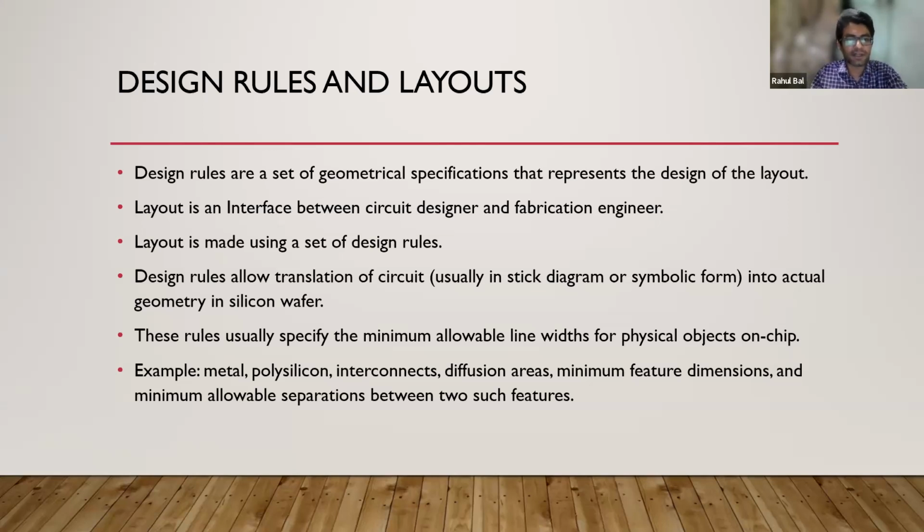That's why it is the interface between circuit designer and fabrication engineer, and it is made up of design rules. Because if you are designing any layout, it should have some rules. And these rules usually specify the minimum allowable widths for physical objects on the chip.